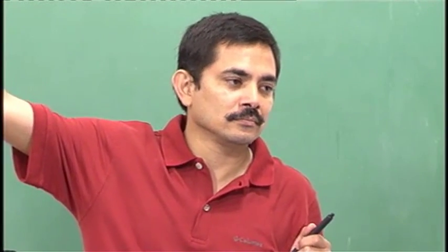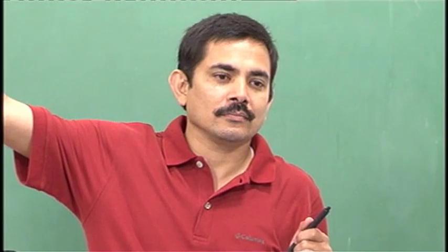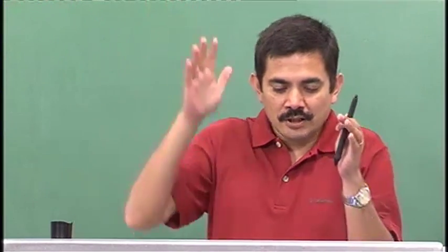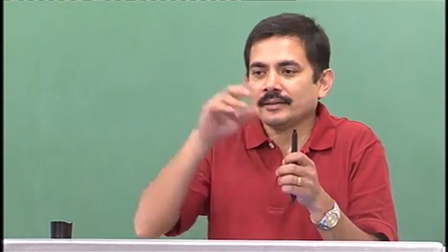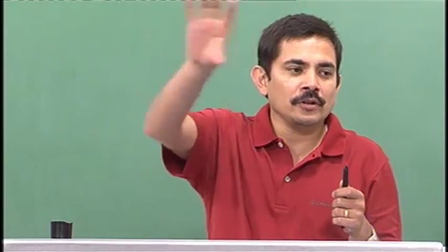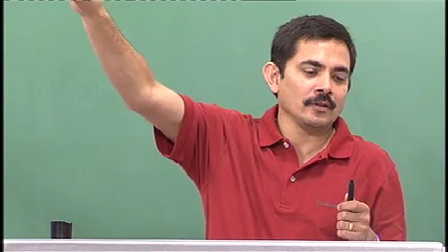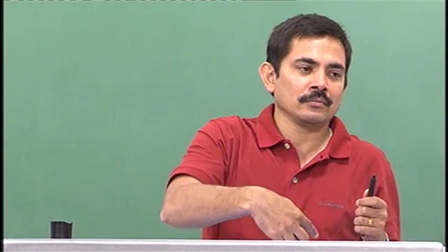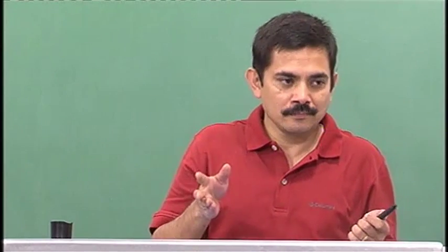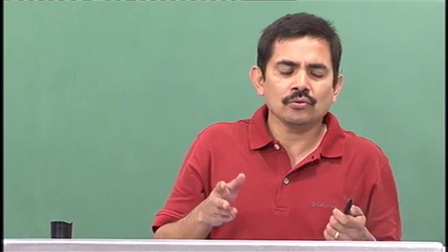Yes or no? So you started, I have so much degree of freedom. What are the production objectives of the plant? That then tells you that, oh, look, these are reasonable variables to exhaust those degrees of freedom, these are unreasonable variables. Specifying FA and FB together independently is unreasonable. Okay? And so on and so forth.